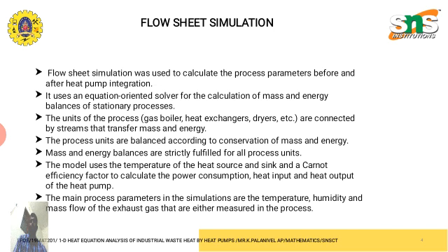The setup implemented in IPSE Pro corresponds to the actual setup of the different processes. The units of the process, gas boiler, heat exchangers, dryers, etc., are connected by streams that transfer mass and energy.